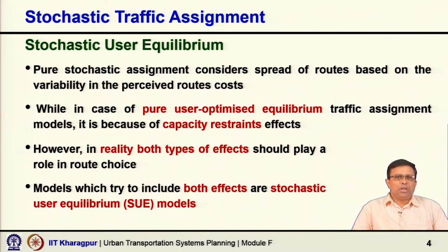And even when the demand is less than the capacity, the demand is still very significant. So, there will be a congestion effect, and because of that the path will no more be the shortest path once the flow is assigned, and alternative paths will be used. So, in pure user optimal equilibrium, UE, multiple paths are chosen because of the capacity consideration, because of the congestion consideration.